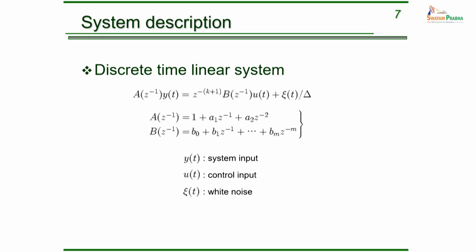Okay. So let's look at the following discrete time linear system. This is similar to the ARX process that we identified earlier. It is A y equals B u with the delay for the input, plus C divided by delta. So this term is slightly different than what we've considered earlier. In earlier examples, we only looked at white noise. This is known as integrated white noise.